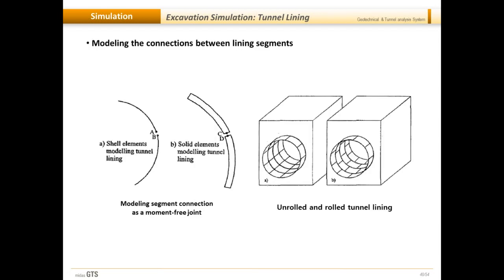So this is how you model tunnel lining. But what about lining or the segments which are prefabricated and they have connections between them? This problem is largely looked into by structural engineers, and what structural engineers do here is that they model it using shell elements, and at node A and B, if they are released for movement and they are not transferring any movement, there's just shear and axial force, they couple the behavior of these two nodes so that they can transfer just the axial force and shear but not moments.